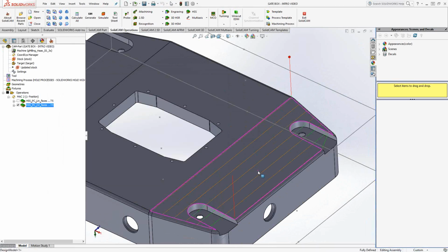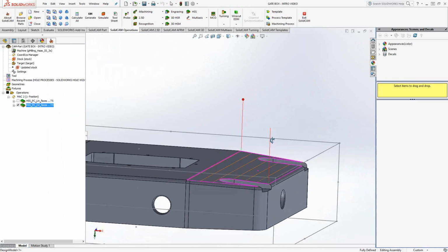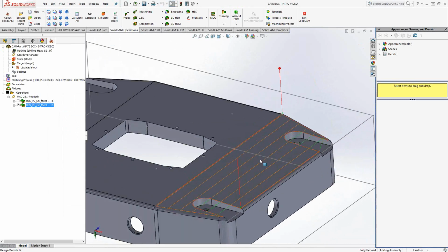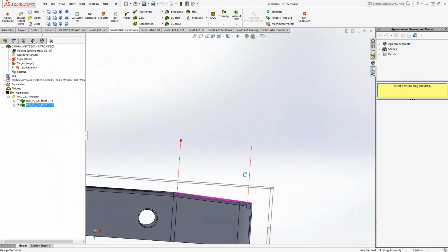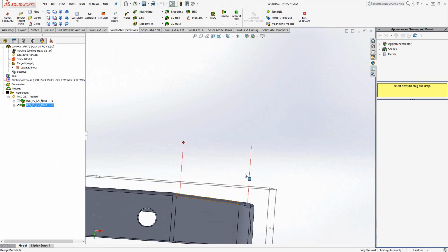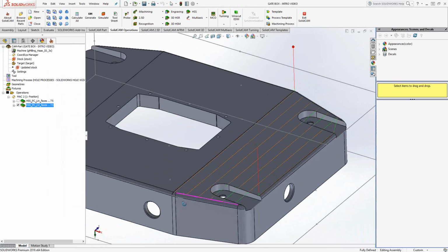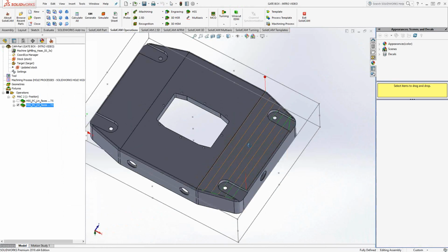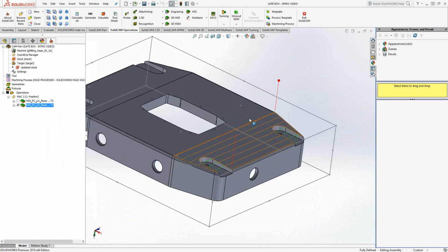That is actually not a good toolpath because you can see that it's very spaced out. That's because the 20 thou, as I mentioned, is in the Z direction. So those two lines of passes are actually Z.02 away from each other. But if we look at it from top view, that actually fans out a little too much. So for this toolpath, I probably wouldn't actually use a constant Z toolpath. So that is how you distinguish linear versus constant Z.